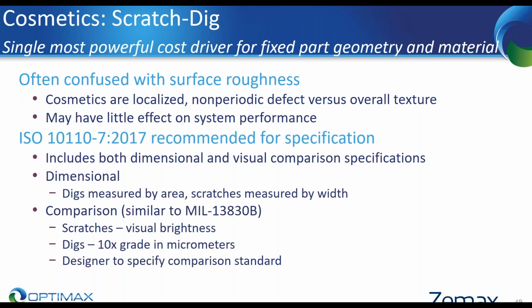Next up is surface roughness. I mentioned earlier, surface roughness is the measure of the texture on the surface, and it influences the scatter in the optical system. And so controlling the surface roughness is important for a lot of systems. Typically, it's measured by surface profilers. A white light interferometer is the most common. There's a schematic diagram of one in the center there, and then on the right is a resulting phase map image, a false color phase map image of polishing marks on an optical surface.